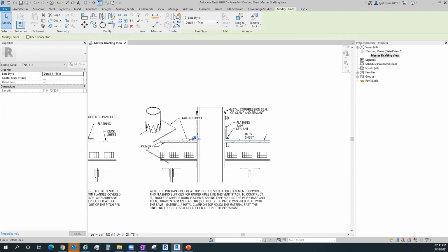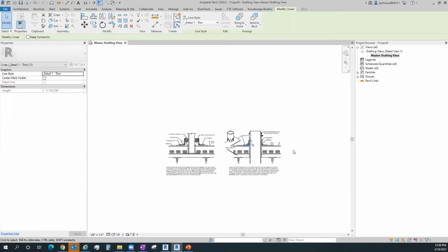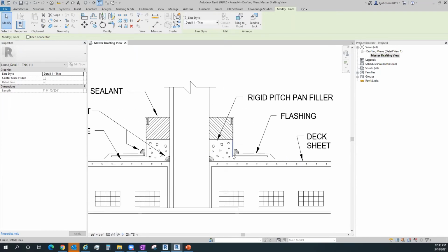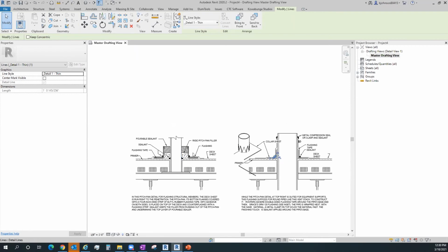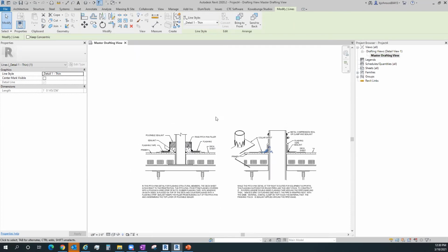So once I realize what the majority of those fill patterns are in my blank template, I could add those fill patterns in, maybe transfer them in from a different project or something like that, and then be able to just swap them out with the proper fill pattern style that I want, whether it's a left angle or right angle on the 45s or whatnot. I'd probably have to have individual patterns to make those work correctly, right?